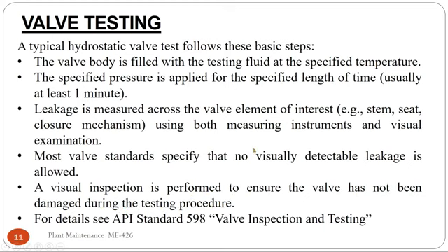So, fill the fluid, apply the pressure, retain it for 1 minute, check the leakage across different elements. If there is no visual leakage, then it is okay. After the test, open the valve and check it, because there is a chance that due to applying pressure there may be a crack or something else. So we can see the video of the testing.